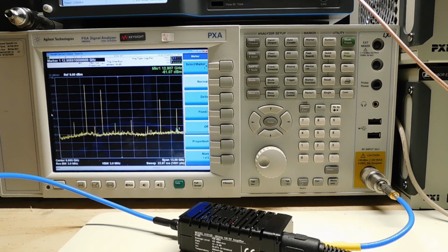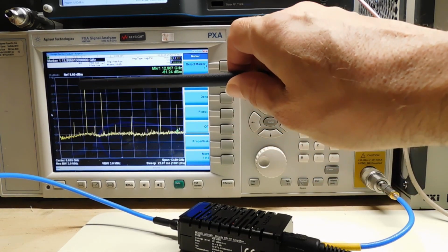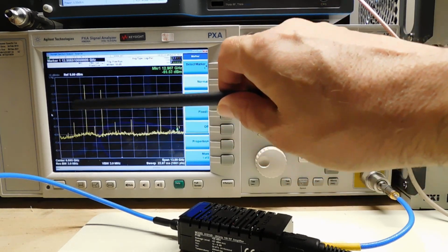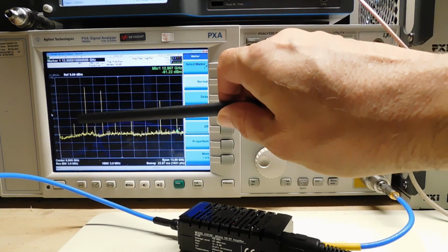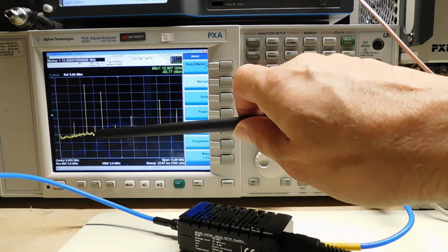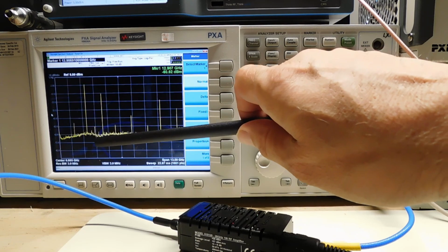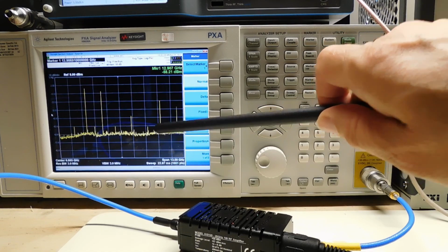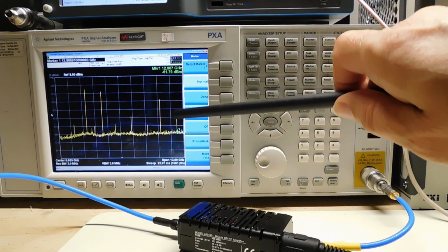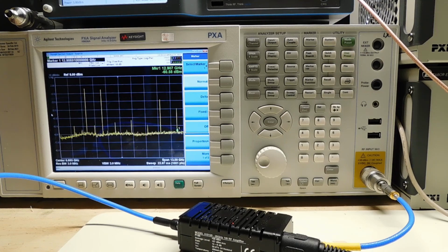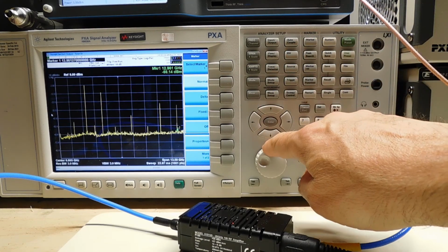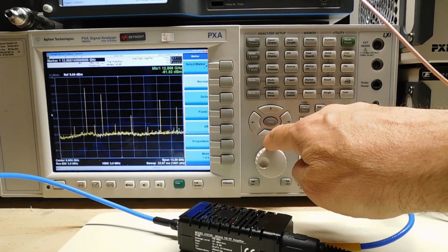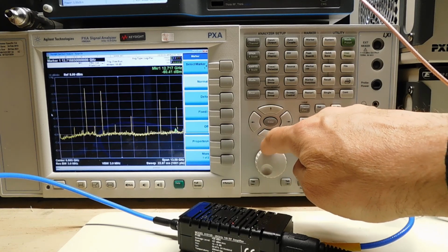I've tuned the center frequency of the arbitrary waveform generator to 3.6 gigahertz. And so what we see here is our 75 megahertz original Gaussian pulse, now modulated on a 3.6 gigahertz carrier. Here is clock minus the 3.6. Here is clock plus 3.6, and here is 2 times clock minus the 3.6. So if I just wheel the marker around here, you can see we've got a pretty nice signal here at around 12 gigs, 12.8 gigs, 12.9 gigs, 13 gigs.